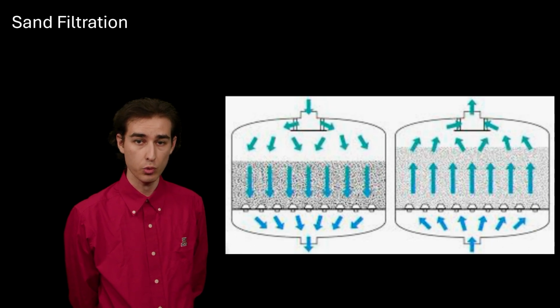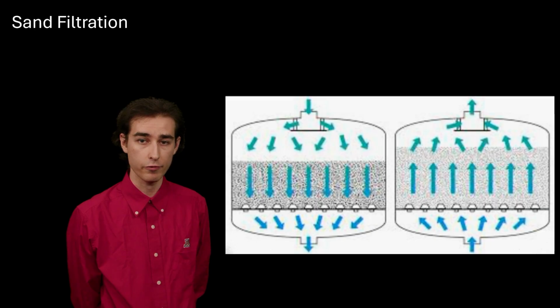As the filter is active, it will gradually accrue scale and hardness from the water. To prevent the media from becoming a solid mass due to the buildup of minerals in the pore spaces between individual particles, the system must engage in frequent backwash cycles to break up the media and remove any solids suspended in the water or attached to the media.